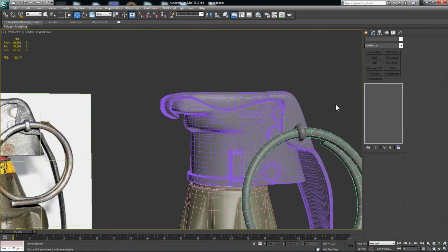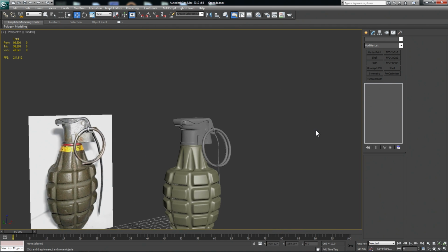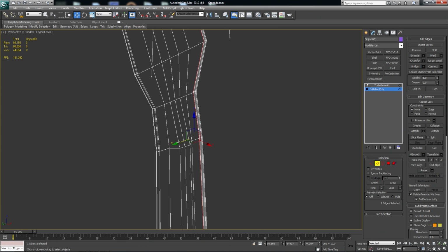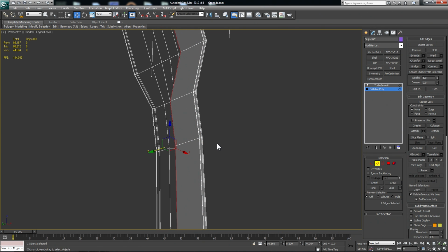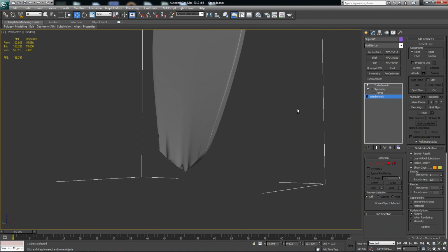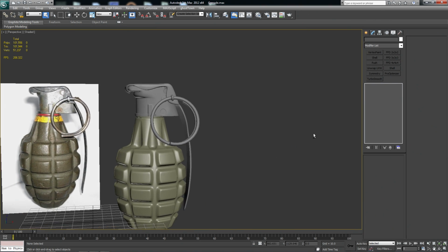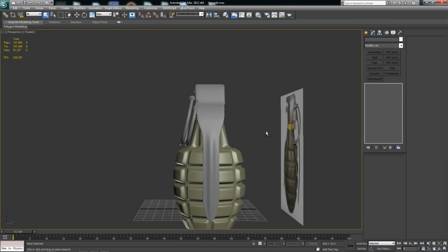Okay, now the last thing to do on the high poly is to surface the backside of this safety lever, so you can just shift drag them inward and then add a new symmetry if needed. Now I'm having some nasty smoothing right at the bottom, so I need to clean up this geo and adjust the mirror axis of my symmetry. I also need to manually cut in some supporting edges from this bottom edge. Okay, awesome. That wraps up the high poly portion of this exercise.